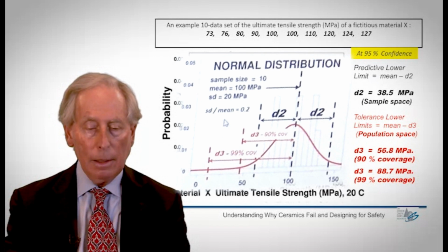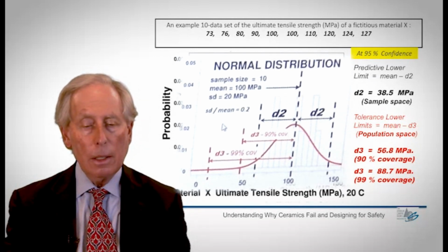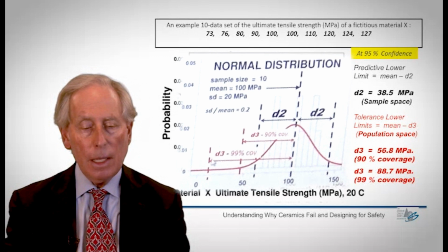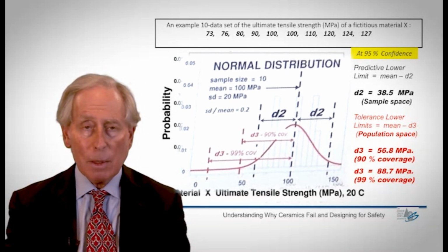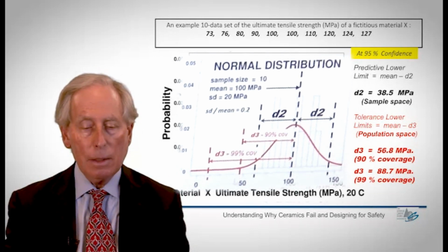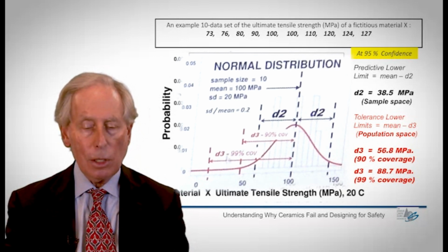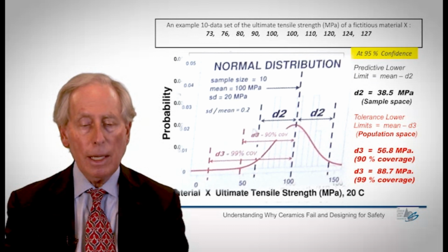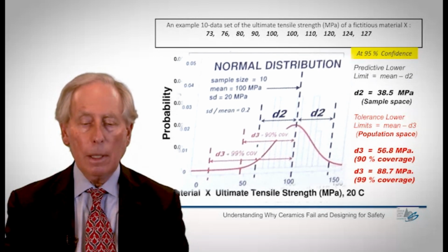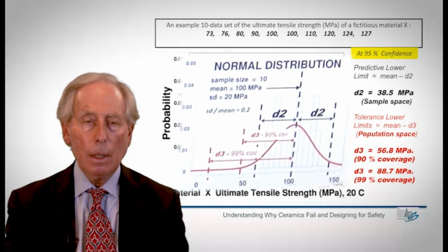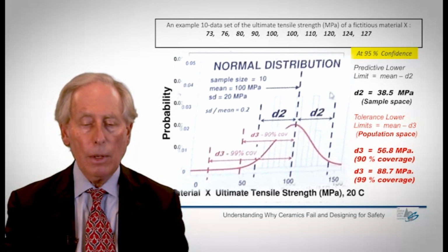I should be designing. And if I wanted to reduce the set of these numbers, I can test more specimens. This will, by nature, reduce the sizes of all of these numbers. I can reduce my desire to have absolute certainty by using 90% confidence levels. It's up to the individual, but the data is there, and the statistical analysis is there to get you to the point where you have some confidence in the number that you predict.